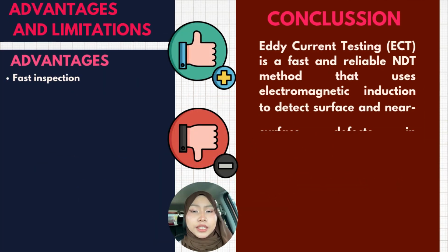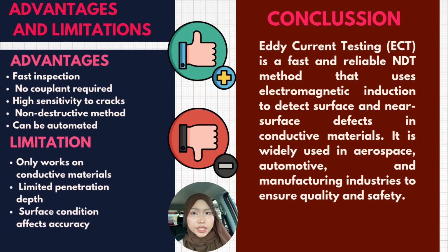Finally, let's look at the advantages and limitations of eddy current testing. Some key advantages are that it provides fast inspection, does not require a couplant, has high sensitivity to surface cracks, is non-destructive, and can be automated for efficient testing.